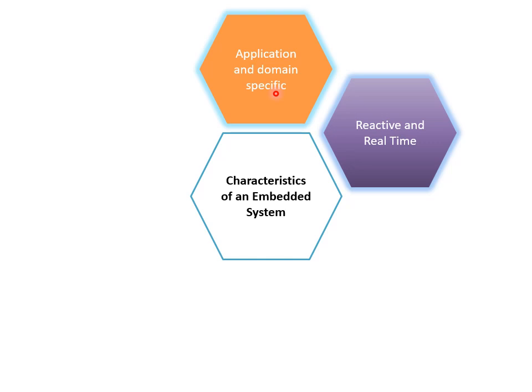This is the basic flow of functionality of an embedded system. We know that. But what is challenging here is that the changes happening in the real world may be periodic or aperiodic, meaning unpredicted. We call such changes an event. So the event may be periodic or unpredicted. If your embedded system is expecting an unpredicted event, then such a system should be designed such that it is scheduled to capture such events without missing them. So we say embedded systems should be reactive systems. They should react to the event happening in the environment then and there.